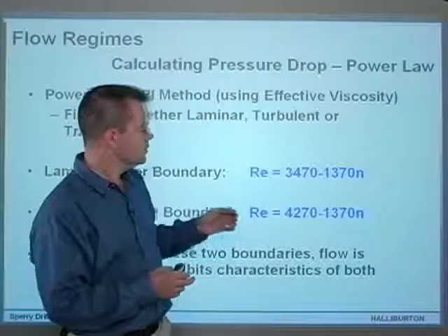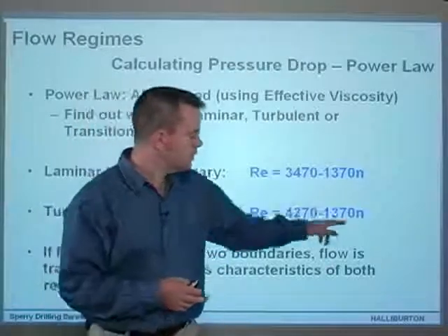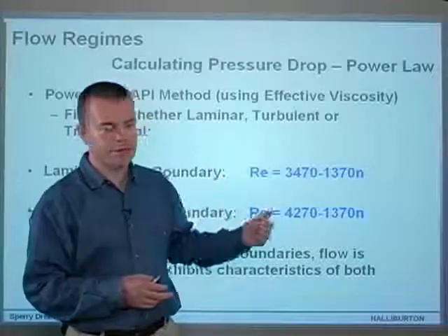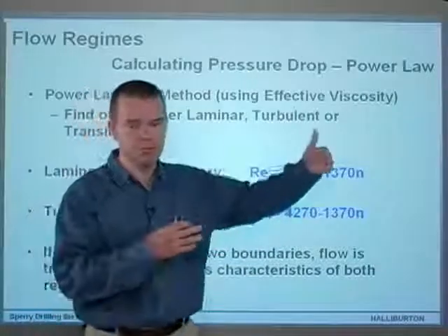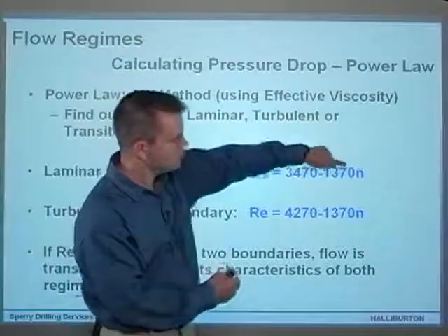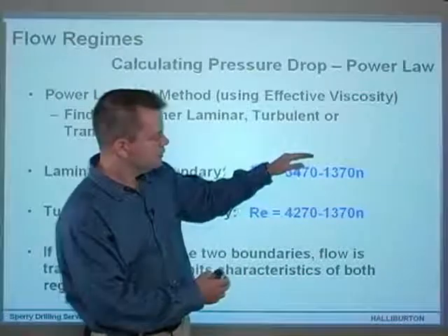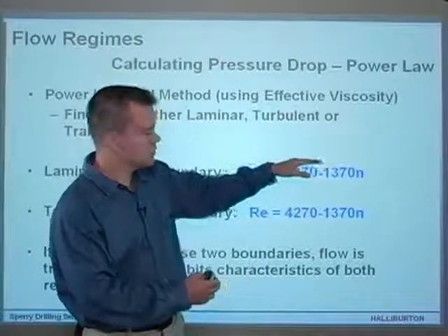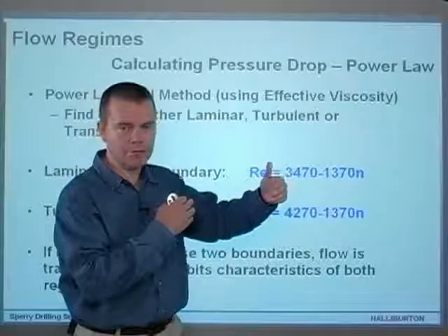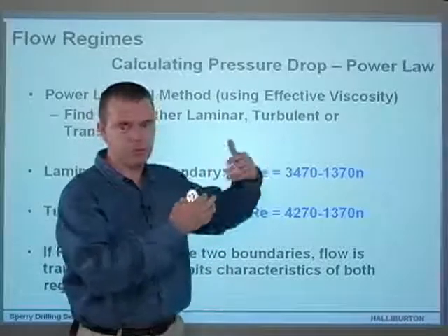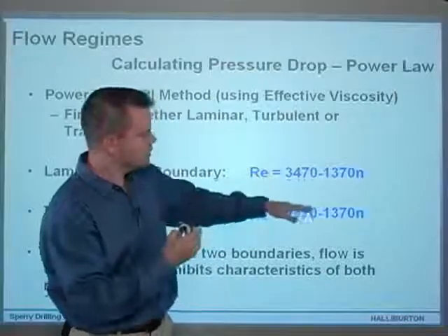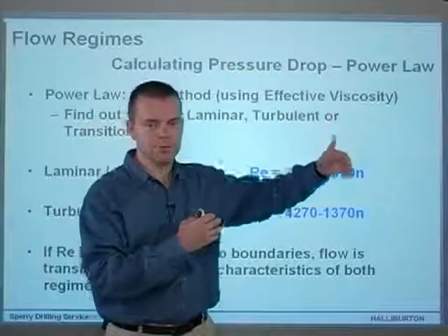And the onset of full turbulence would be 2900. So somewhere after 2100, when it crosses 2100, it's no longer purely laminar. It's now intermediate or transitional flow. When it gets to 2900, it's fully turbulent.